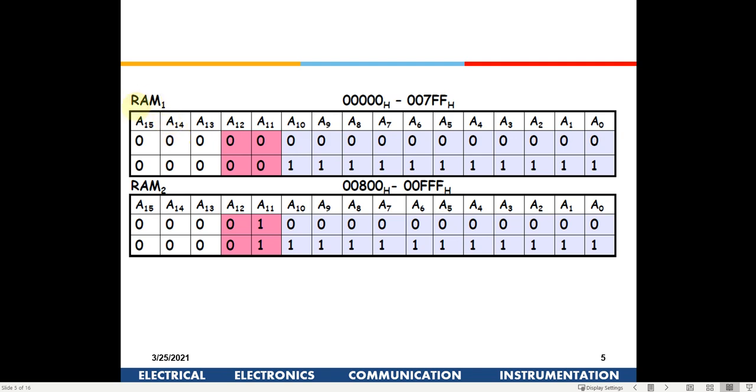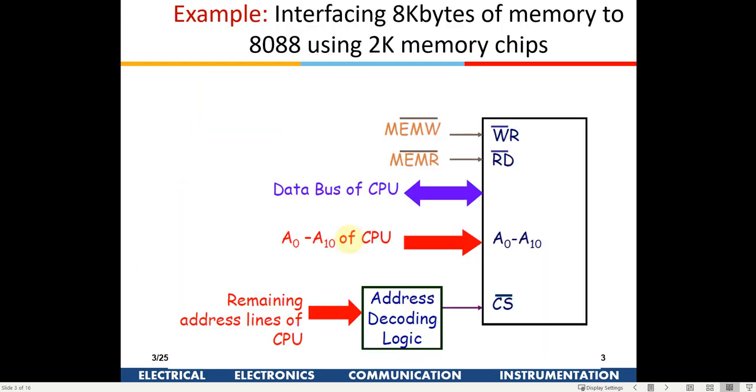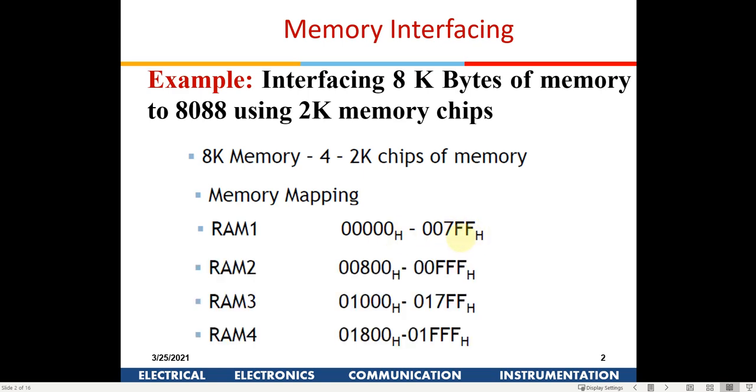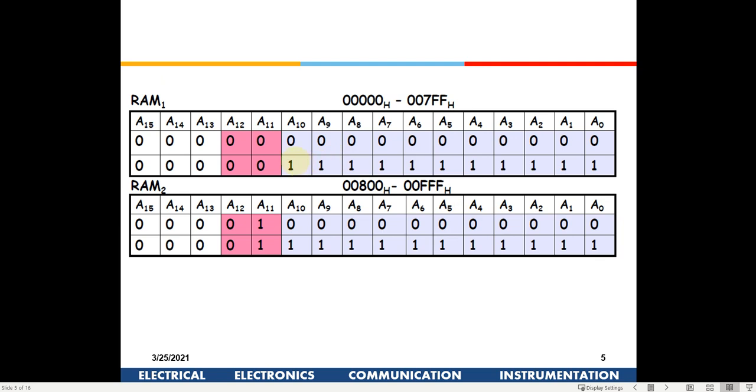And then we design RAM 1, RAM 2. These are the data and address lines corresponding to each of these RAMs. Now you have to give a unique value here for each of the RAMs. So we start with 00 for the first RAM, and you can give 01 for the second RAM. These 10 lines are required since these are the 10 different unique values for each RAM.